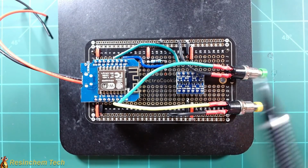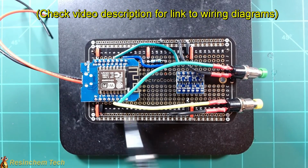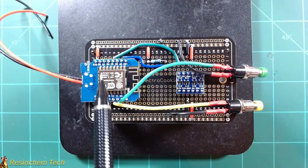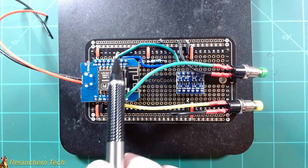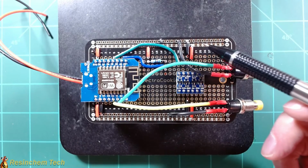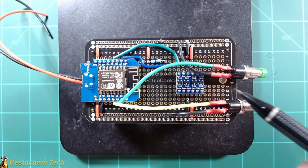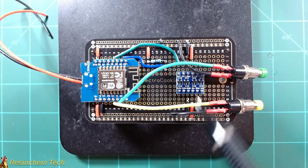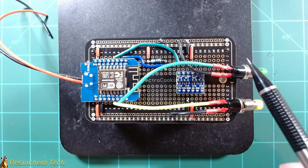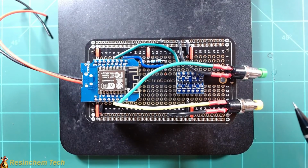But I did wire a normally open push button to D1 and ground, and another push button to D2 and ground. And underneath here, you can see that I've got the logic level shifter in place, and I have a data line for future LEDs coming off of D5 into my logic level shifter, which is also wired to 3.3 volts and ground on the low voltage side, 5 volts and ground on the high voltage side. If I decide to add LEDs down the road, I'll just need to add a data line and a common ground off of this board to my LED strip. But again, all these push buttons and the logic level shifter are completely optional. You don't really need it for the bed sensor itself.